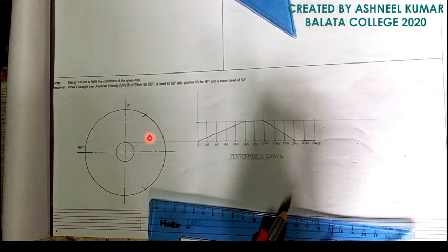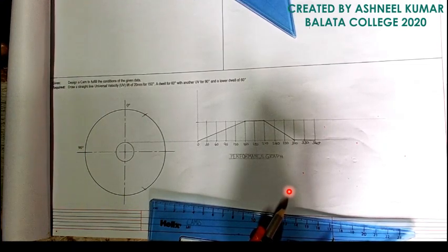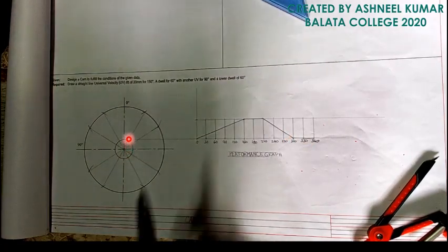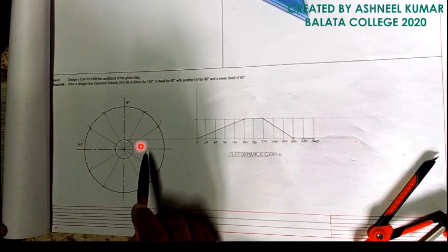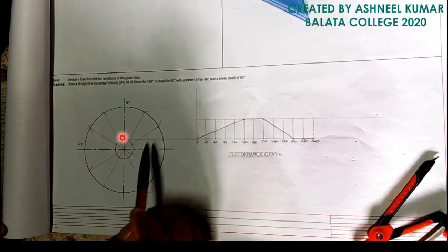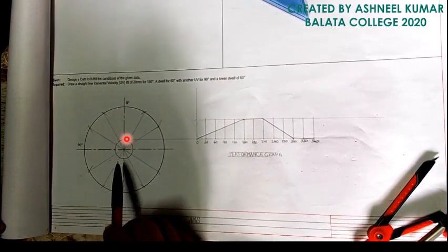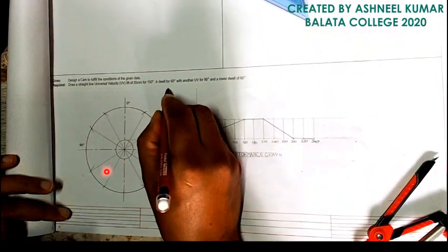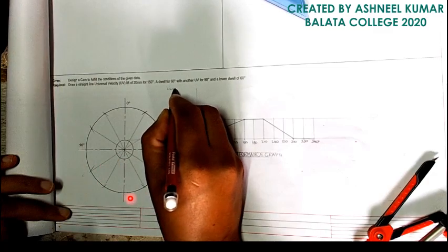Put it here, take the distance, you'll mark it here and there. Then from 90 degrees to there, you'll mark it here and there. And from 0 degrees till there, you'll mark it on this place and that place. After you have done that, you are going to join all the lines passing through the centers. If you have equally divided the circle, you'll see from here to there, they should fall on the same line.